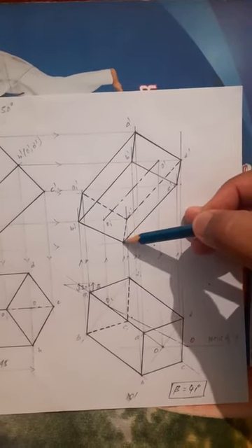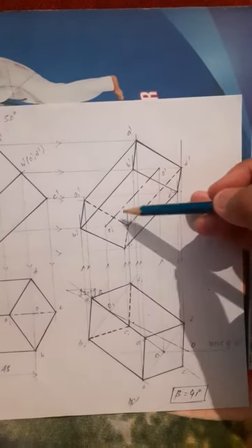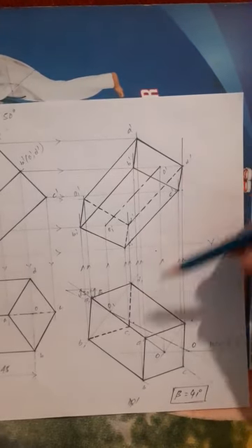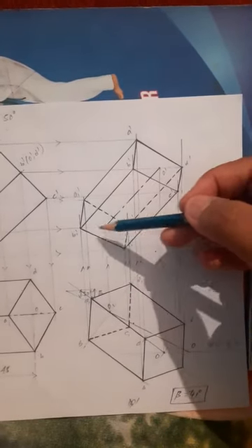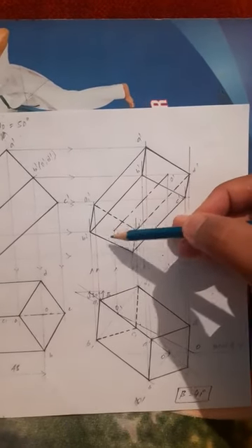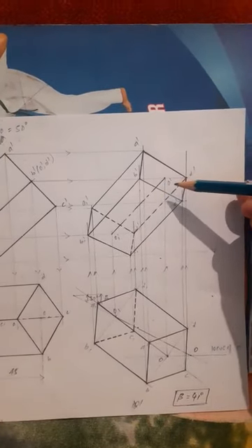D1 dash C1 dash is also a dashed thick line. D1 dash A1 dash is also a dashed thick line. Then measure O and draw vertical projectors for O and O1 dash. Then we get O1 dash and O dash, the axis line, shown with a longer line and shorter line, longer line, shorter line, right?